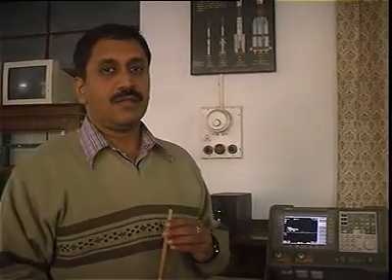Accordingly, we designate them as dBW, dBm and dB mu. When I am talking about absolute power, that is, I am looking at a particular frequency component, how much power it has got, I will say that this frequency has got so many dBm of power.